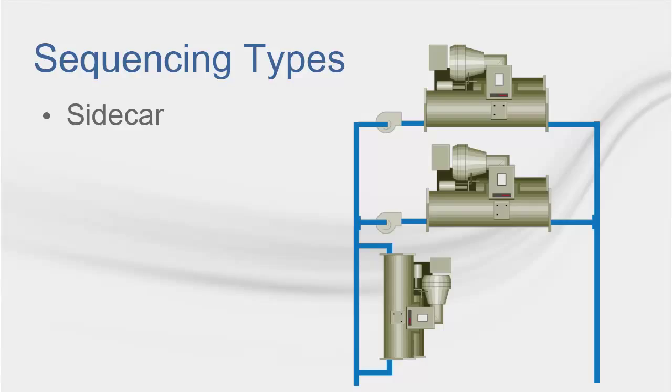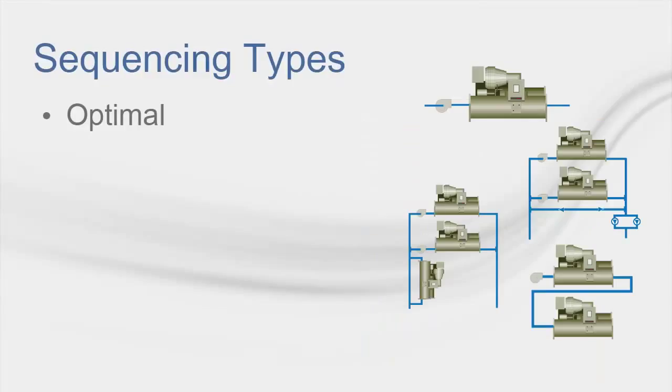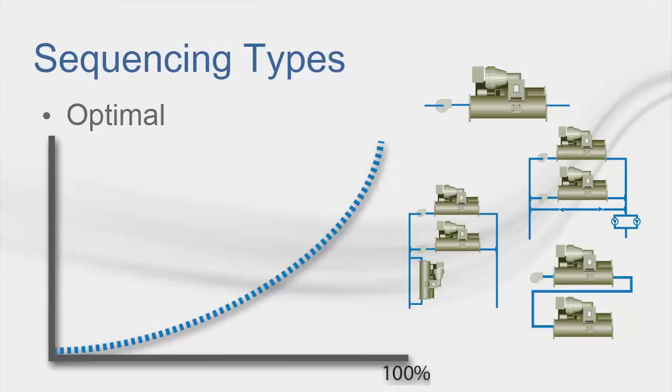must be listed first. Finally, with version 6.3.2, we have added optimal sequencing. Using this optimal sequence allows the program to operate at the best part load condition using the power consumed curve to run the chiller at this point whenever possible. As such, this will set a sort of limit so that once the chiller hits this point, it will maintain this part load condition and enable additional chillers as required.